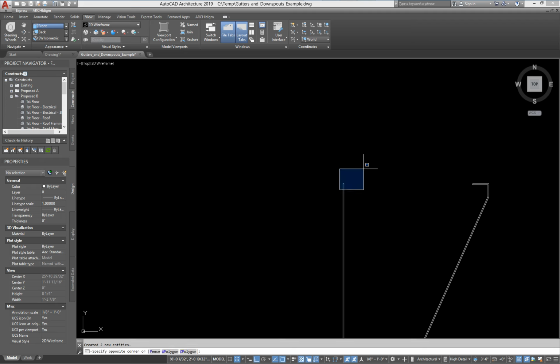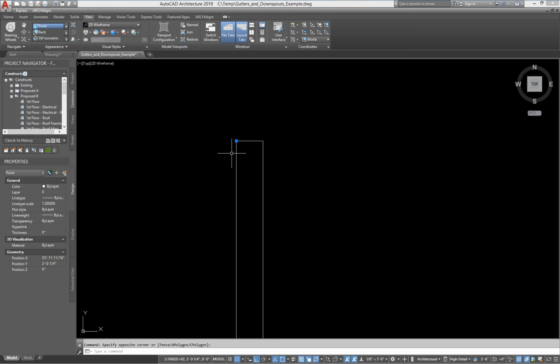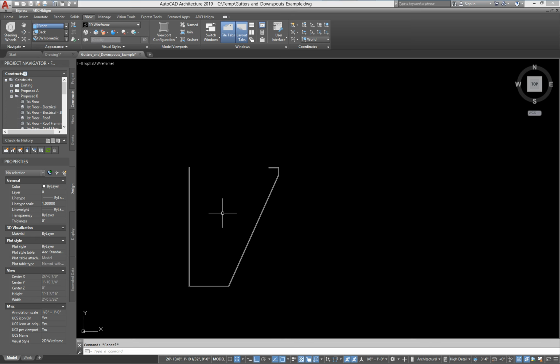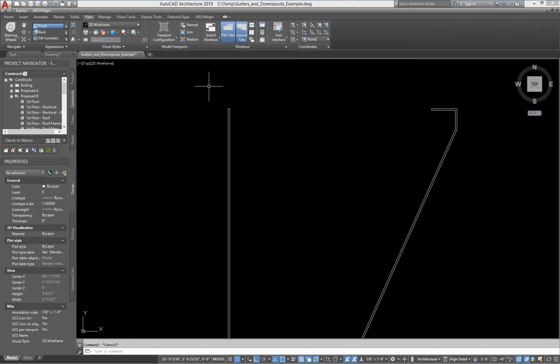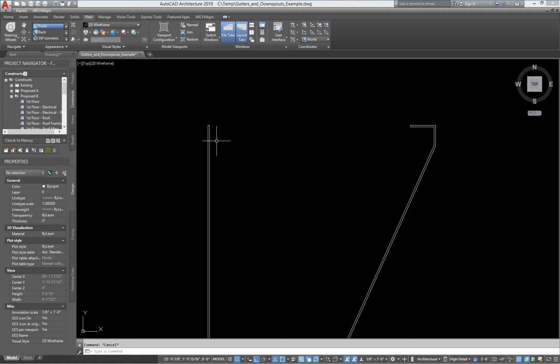And it brings in a point right there, an AutoCAD POINT. That is there to remind you where the insertion point was when it was created. So this shape does not use the absolute center because of the way that you draw it. It's easier to draw it right along the edge of the roof. So that's the insertion point there when you define it.